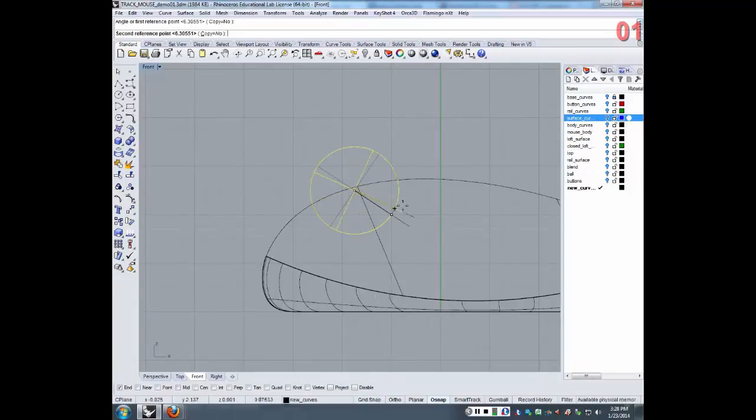Let me turn off my grid snap. I'm going to rotate it so that it's like that. And you should always make sure that your hemi, the hemispheric line, is below the surface of your object. Anybody want to tell me why? It'll fall out otherwise. That gives you the mold lock that you need to lock it in.